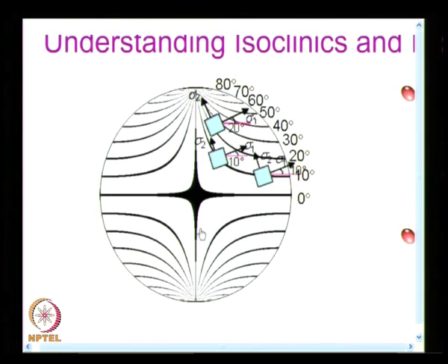You have to extract data by several different positions of the polarizer analyzer combination. You do not see this information available in one experimental exposure. This is what you have in conventional photoelasticity.